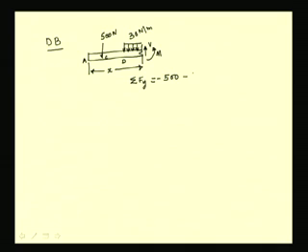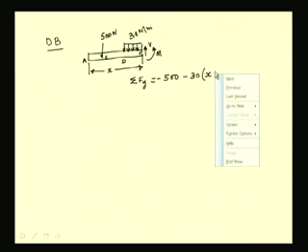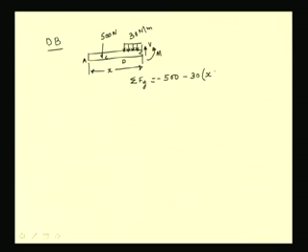So, minus 30 times x minus the distance AD, which is 10, plus the shear force V equal to 0. So, from this we get V as 500 plus 30 into x minus 10 newtons.